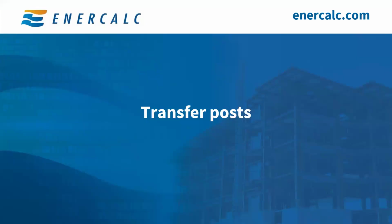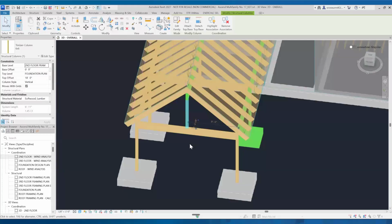Now, I do want to touch on the concept of transfer posts, which are highly adjacent to columns. We are doing them using column calculations, but instead of the column bearing on a foundation, it's bearing on a superstructure element that's somewhere further up in the structure. And this is actually something that structural engineers run into a lot, regardless of what kind of building you're doing, whether you're doing wood structures, whether you're doing steel structures.